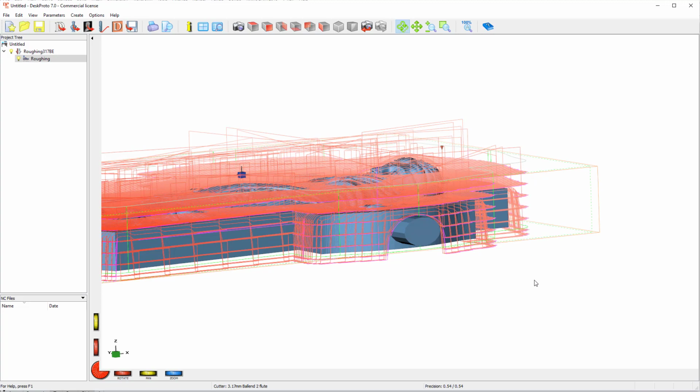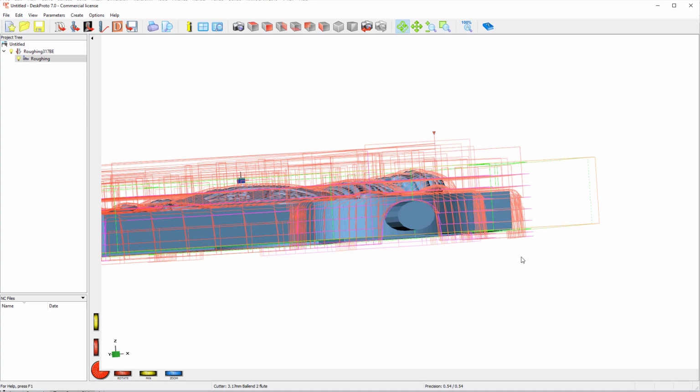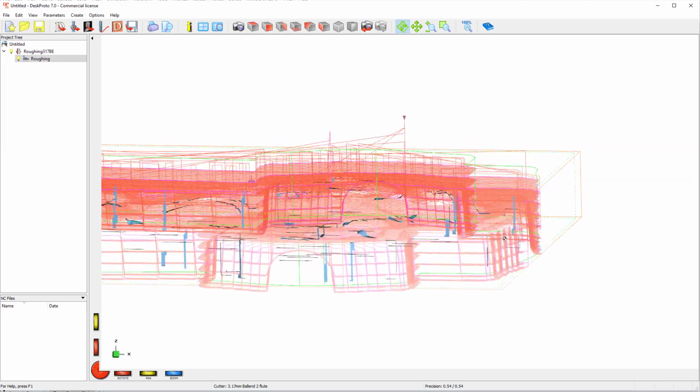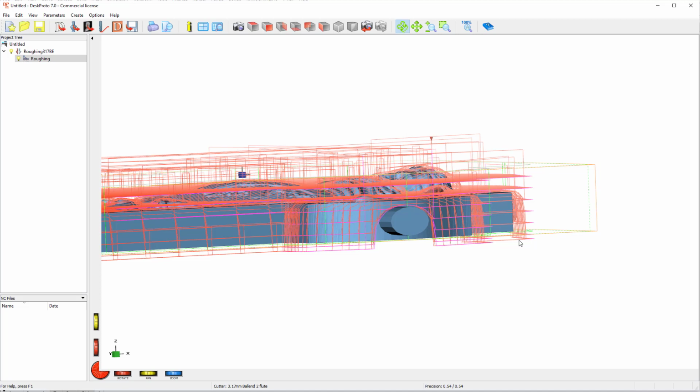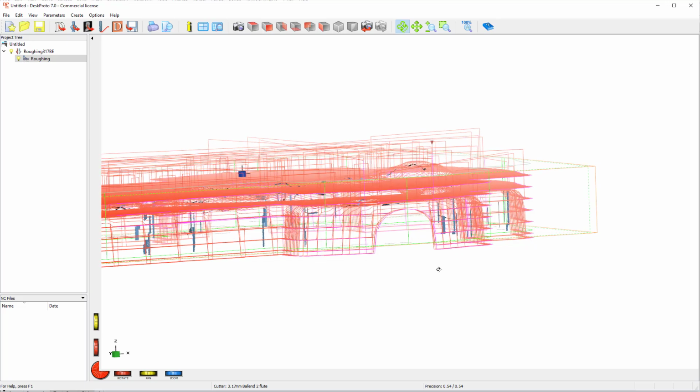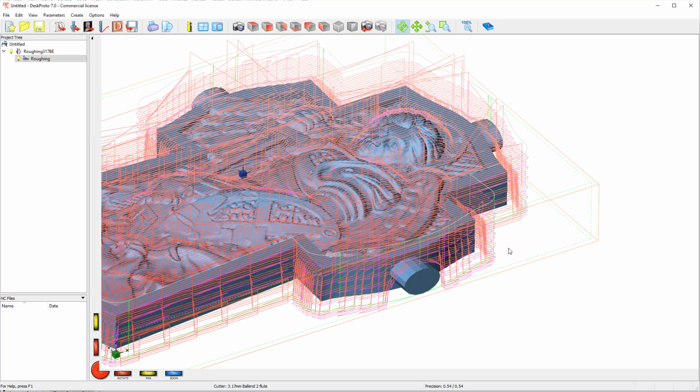And it's coming in a little bit low for my liking over here, so I've got to make sure I've got enough material inside there to do it. If you were a smart guy, you'd measure the height of that, divide it into maybe 6 steps, and then put the exact step depth into the depth of cut down. But for now, for the wood, I'm not too bothered about this.